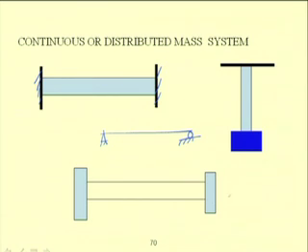So, this is the example of a two rotor system. Two rotors are mounted at the end of this shaft. In this case, one can observe the body will have an infinite number of natural frequencies if the mass of the system is taken into account. Otherwise, one may find two natural frequencies of the system by considering only these two masses.